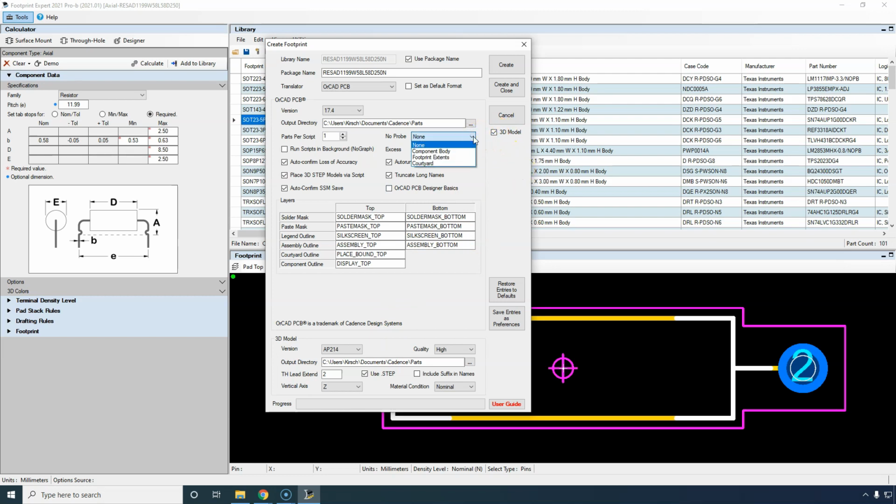No probe. No, that's fine. Then what is no probe? No probe means that you can set a rule that says don't put any test points under this device or around this device. And that comes in handy for bed of nails testing and stuff like that. But generally I define that within the software if I don't want certain areas tested.